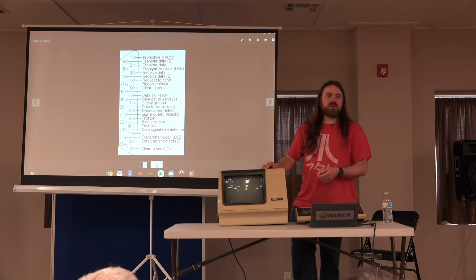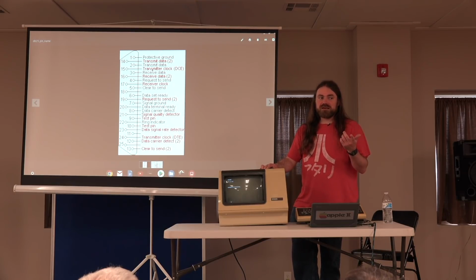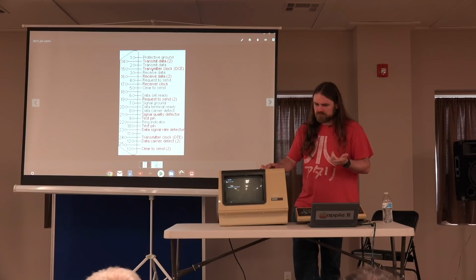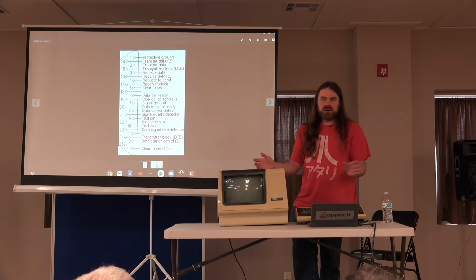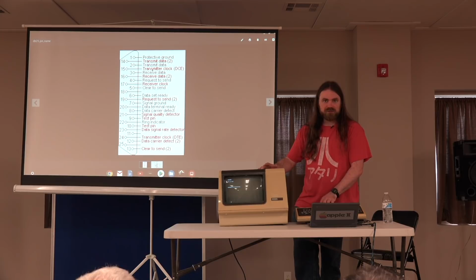And Jason Perkins can tell you all about that because the Lisa keyboard uses that, as does the Sol 20, the TRS-80 Model 2, the Compact Portable, Cume terminals, and some of the ADS Viewpoint terminals. You find those capacitive foam keyboards everywhere, and they're all dead now. So if you get a terminal where none of the keys work, check to see if it's that foam kind.